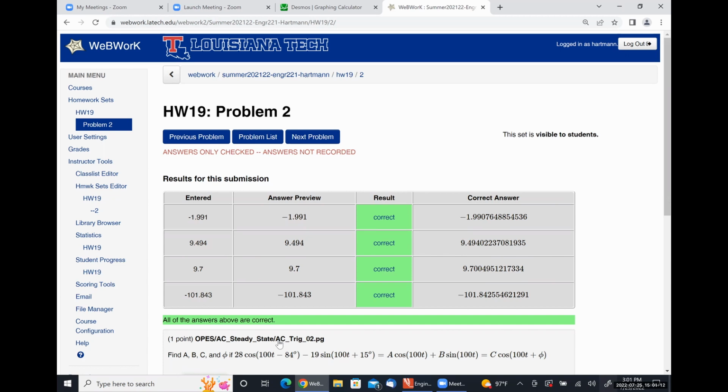What we're going to be talking about for literally the remainder of the class effectively is what's called frequency domain circuit analysis, where we take a time domain circuit like the one that we started off with, and then we work it in the frequency domain just using complex numbers and wind up getting the same result as we would get if we had worked it all using the sinusoids. So I'm going to spend the next couple of minutes explaining why that is, and then I'm going to stop talking.